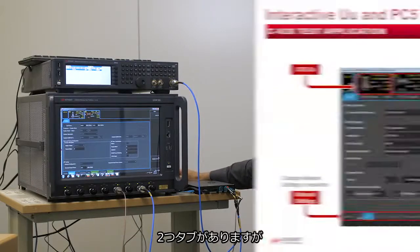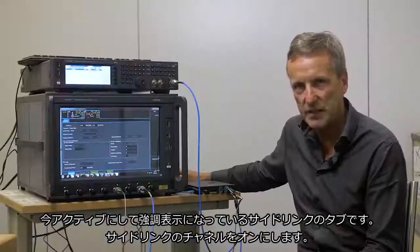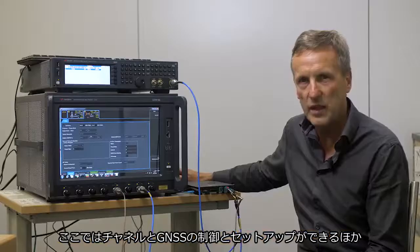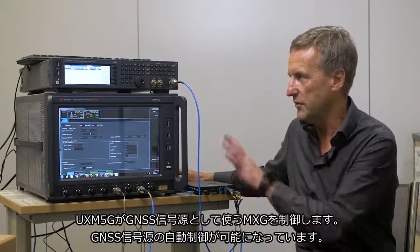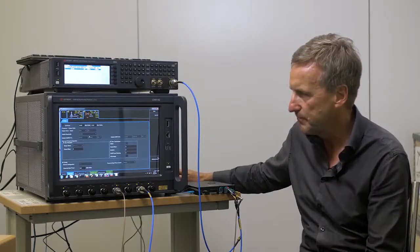Here we see we have two tabs. The first tab is for our LTE connection for mode 3. The second tab here, which we have active, is our side link tab, and we can see it's highlighted. We have the side link channel on. We can see here that we are able to control and set up the channel as well as GNSS, and the UXM 5G controls the MXG for GNSS, so we are in full control right now for GNSS.